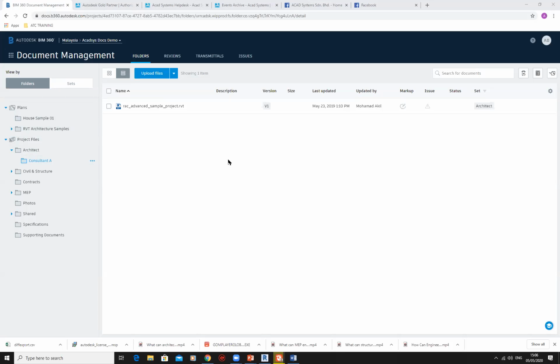Another question: we read somewhere that we can do bulk upload, but when I tried sometime last year, the uploading never got through. It was left for 4 hours and still showing uploading. If you wish to work with bulk uploading in BIM360, you have to work with a very strong internet connection. The minimum internet speed required is 25 Mbps.